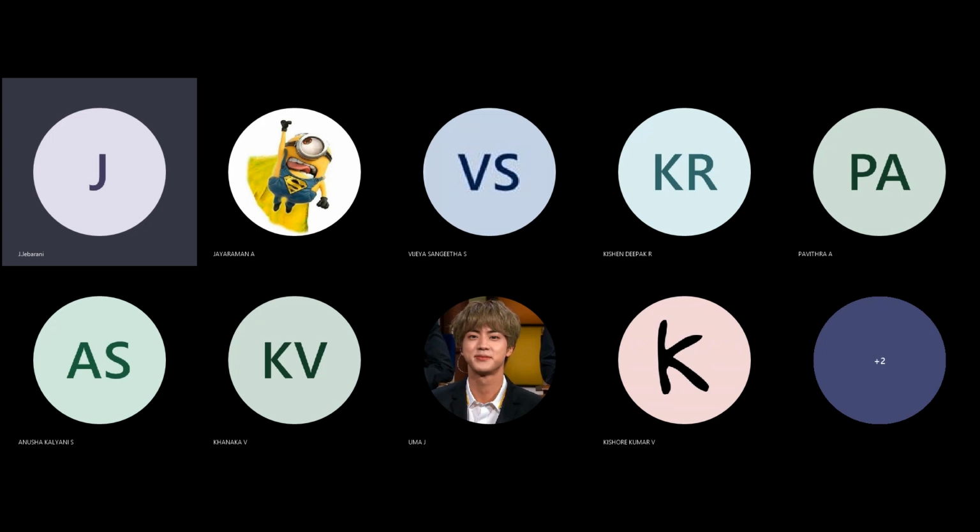So this membrane forces the molten material forward, instead of the polymer forcing the water to the side. The primary reason for this action is the higher viscosity and incompressibility of water when compared with gas. So this viscous front acts as the ram that cores out the part. The front also cools the melt as it is pushed down the mold cavity by water pressure.